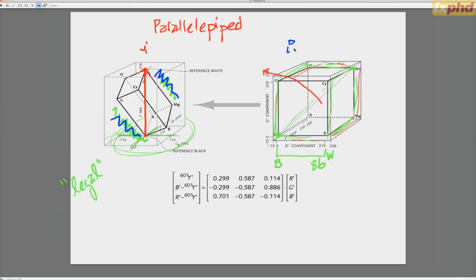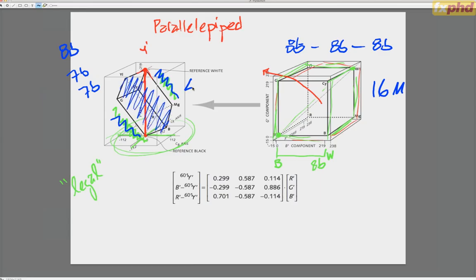So basically, if you go from 8-bit, 8-bit, 8-bit RGB, really you've only got 8-bit luma and 7-bit CB and 7-bit CR. So you do lose some nuance in the color. Or another way of thinking of it, you start with 16 million colors, but the RGB cube here only occupies 4 million codes of the YCBCR space. So there is a little bit of loss in this translation, but we live with it.